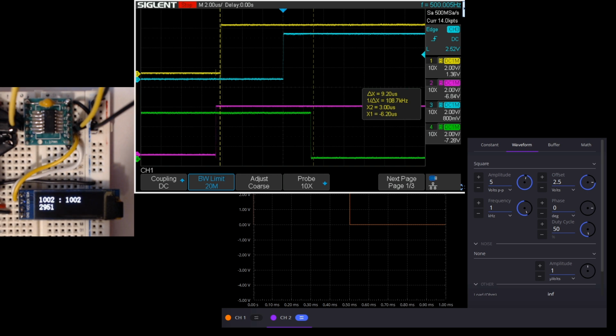And then you can see that there's a time lag between the IRQ signal rising edge and the time of the toggle of the IRQ1 pin. So we can measure that using the cursors at about 6.24 microseconds. And notice that the toggle 2 happens after the toggle 1. So the green trace is changing state after the blue trace. And that has to be the case because the ATtiny has only one core. It can only run one interrupt service routine at a time.